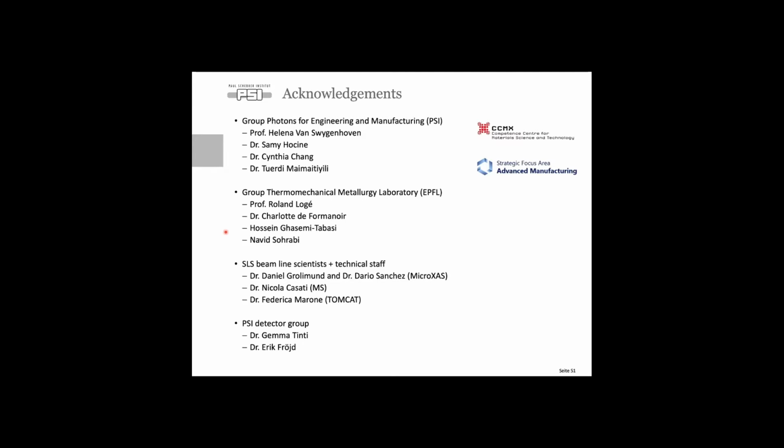Right. So basically, we for sure have also this liquation cracking because we have the formation of cracks before the X-ray or the laser beam is hitting exactly where the crack is. So we have the formation of cracks caused by the heat affected zone from the laser, without actually melting that area where the crack is formed.